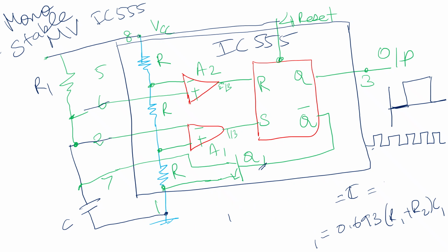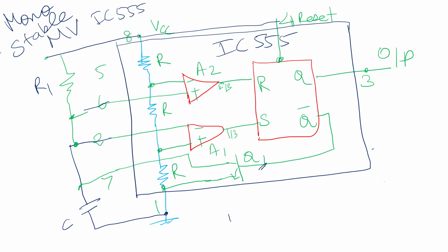So here, when the value of the biasing resistor varies, and depending on the pulse triggering of one third of VCC, the flip-flop is set and a single pulse is generated and maintained at a particular value of plus VCC.